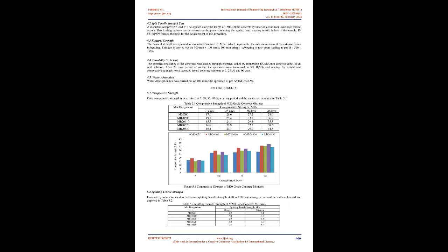The bacteria are incorporated into the concrete while mixing. This type of concrete is called bacterial concrete. It is also called self-healing concrete as the healing process is independent and autonomous. Bacteria become active as soon as they get in contact with water and precipitate calcite, eventually facilitating the filling of minute voids generated on account of the physical structure of the constituents of concrete. This process takes place till there is an availability of water.